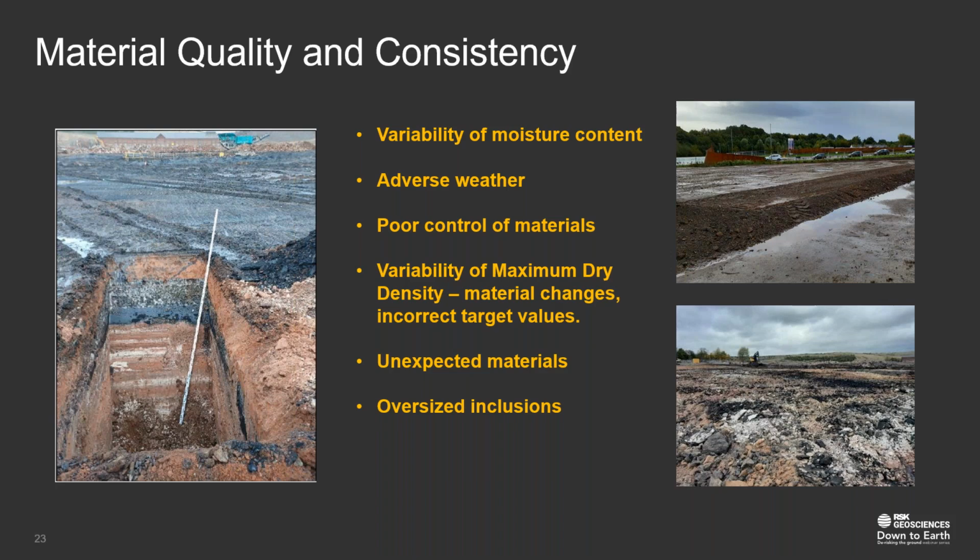But certainly the moisture content can vary with depth and distribution across the site. And I think probably that's the biggest issue with putting material down, is it's either put down too wet or too dry. It's not helped by our climate, and certainly the pressure on clients and so on to work in the winter now. It's quite difficult to keep materials dry, particularly at this time of year.